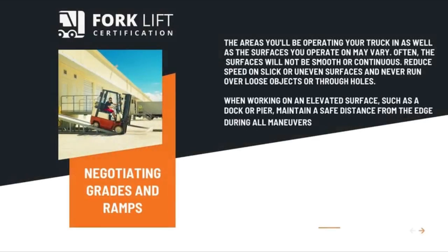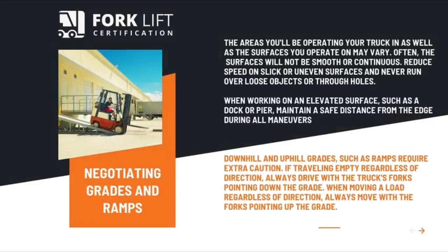Negotiating grades and ramps. The areas you'll be operating your truck in as well as the surfaces you operate on may vary. Often, the surfaces will not be smooth or continuous. Reduce speed on slick or uneven surfaces and never run over loose objects or through holes.